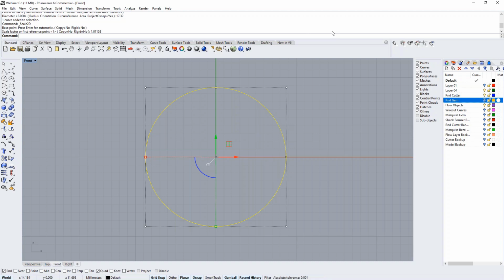What I notice in my particular process, and again, I want to stress that you're going to have to do the experimentation with your printer and your casting process, is that I see a different scale factor necessary for different parts of objects that I create. To explain, this 1.01158 scale factor works perfectly for shanks for me.